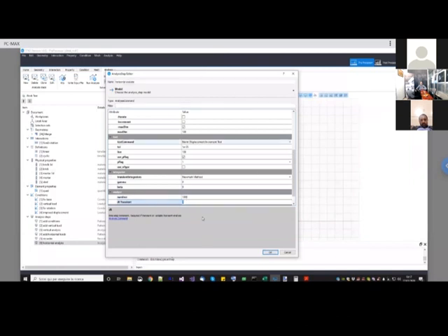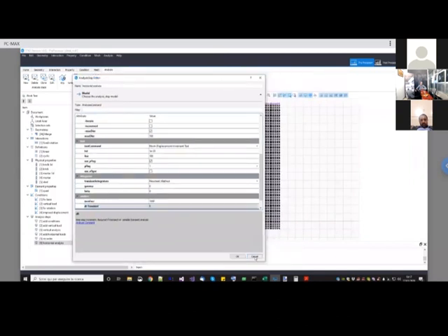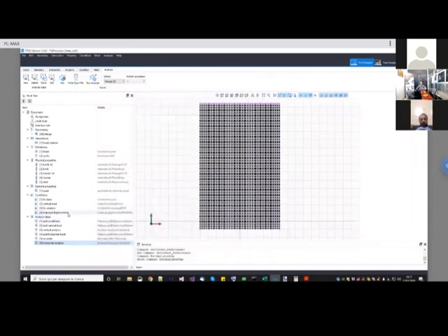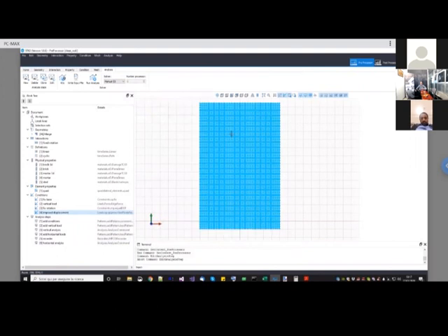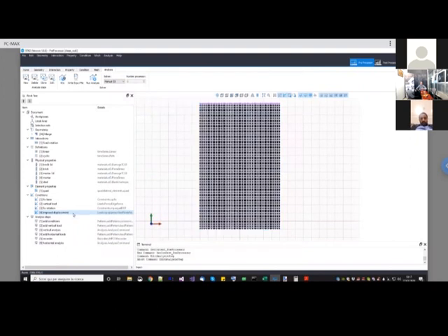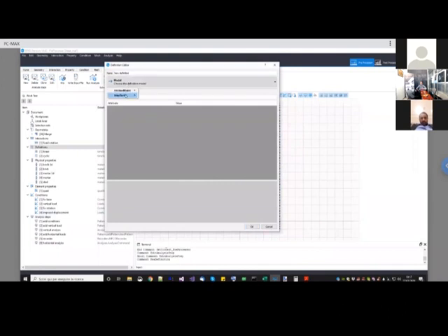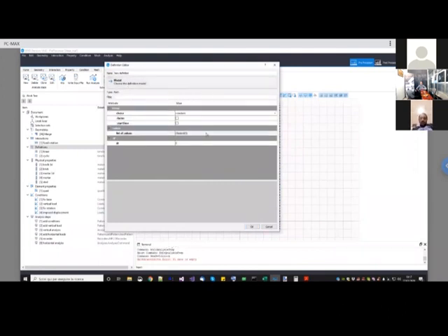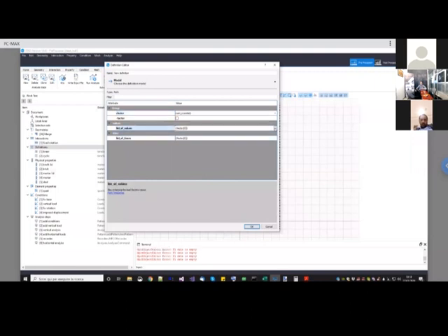So in this case, you just set up a dynamic analysis. Of course, you need to change something in the loads. For example, in this case, my horizontal load was an applied displacement. In your case, it will not be like this. It will be a uniform excitation. So how do you do a uniform excitation? Well, you can first go under definition. You can add a time series of type path. Here on the path, you can go under non-constant, and copy paste here your accelerations and the time step.